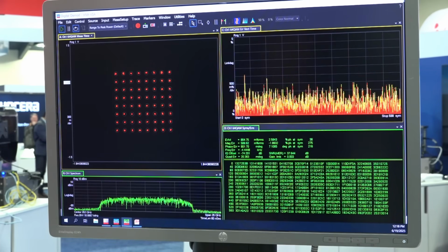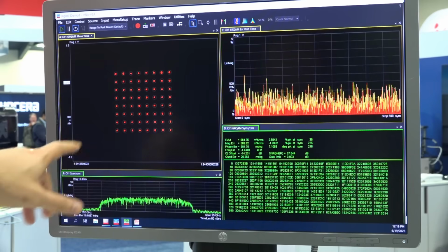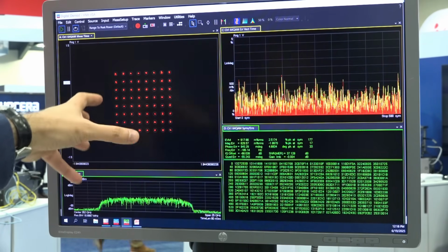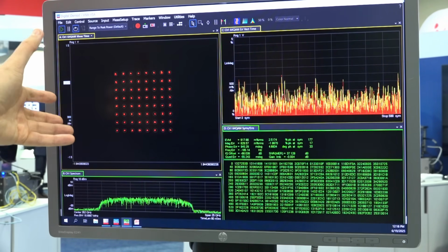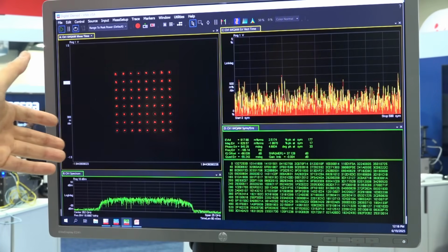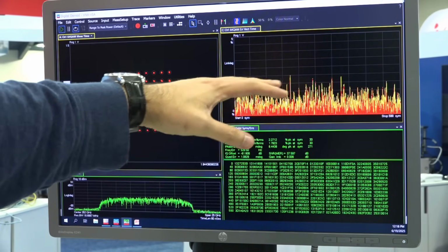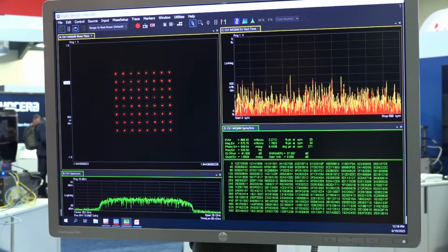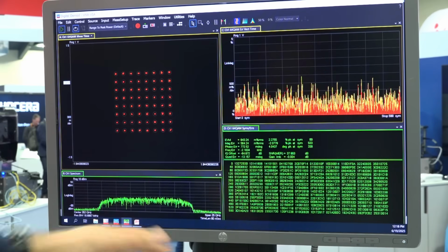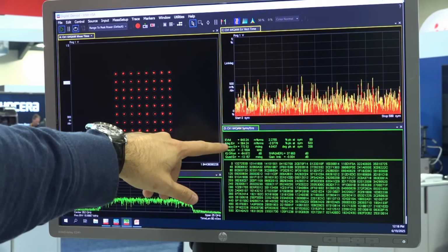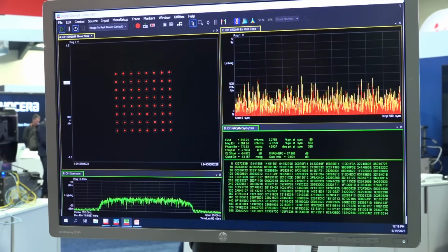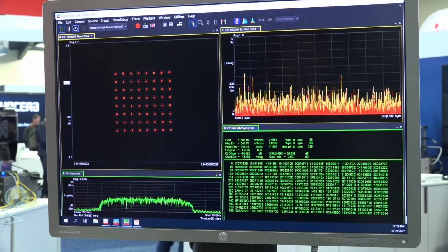And here's a closer look at the Keysight VSA doing this modulation analysis, and you can see that we're talking about 72 gigabit per second at a carrier between 330 and 500. And if you look at EVM as a function of symbol, I mean, it is pretty steady, showing a certain stability of the system. And here's the main number, EVM 0.8%, which is really quite impressive. SNR 38 dB, very good.